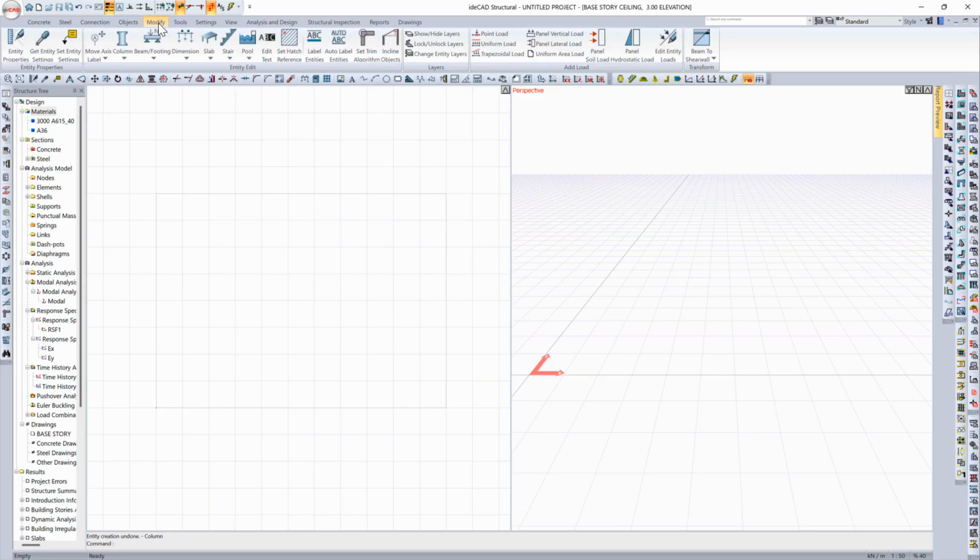In the Modify section, after modeling structural elements, you can directly edit their object properties, or access the same menu by right-clicking the object. For columns, features include short column selection, changing column dimensions, and trimming column shapes. The Modify section also applies to beams, foundations, slabs, and stairs. These object editing tools are available in the ribbon menu.